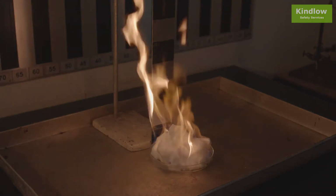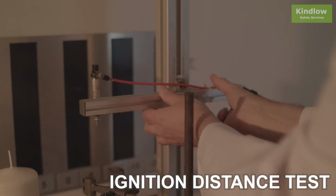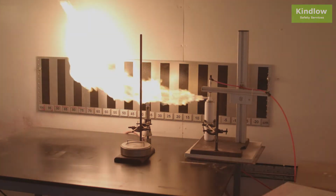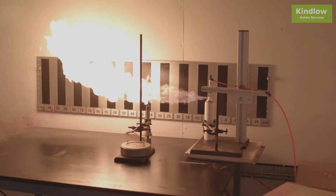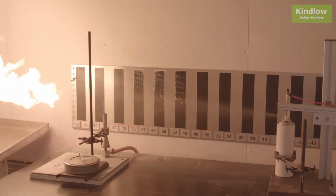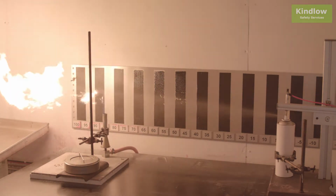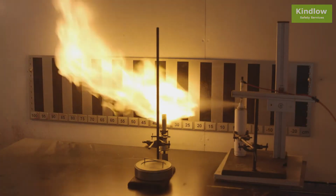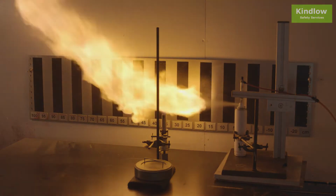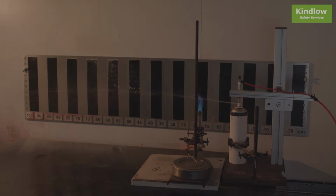The purpose of the ignition distance test is to measure the distance from the spray nozzle at which the flame will ignite the spray as a means to assess the fire risk of the spray. In the ignition distance test, if ignition occurs at greater than 75 centimeters, then the aerosol is extremely flammable. If the ignition occurs at a distance equal to or greater than 15 centimeters, but less than 75 centimeters, then the aerosol is flammable. If ignition does not occur at 15 centimeters, then testing continues with the enclosed space ignition test.